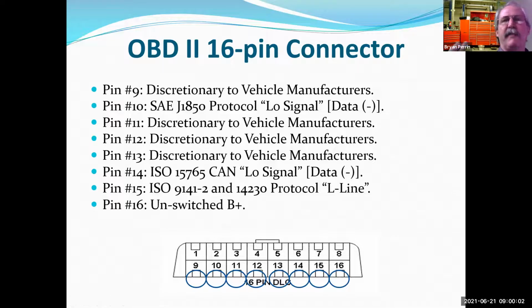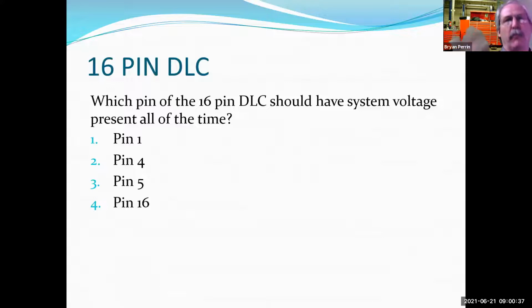Later vehicles might have a dedicated fuse just for that. A lot of vehicles used it for the accessory fuse, radio fuse, cigarette lighter fuse, things like that. So we've seen it lumped in with a lot of stuff, but I do see that fairly frequently. It's the first thing I check anytime I have a communication problem, to verify I have power and ground at the DLC before I start looking for other issues. And certainly over half the time, the fuse fixes it. I mean, well over half the time. Which is why I want you to know that.